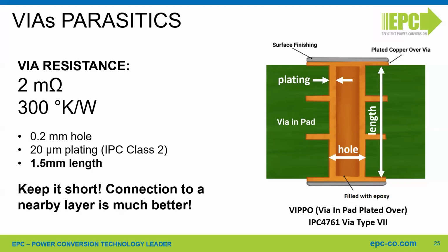Okay. An extension question regarding the turn-on diode. Is it a good practice to use a Zener diode across the gate resistor for additional protection? It's very difficult to protect the gate with the Zener diode because it needs to be placed with very low parasitics, and so it's not very effective.